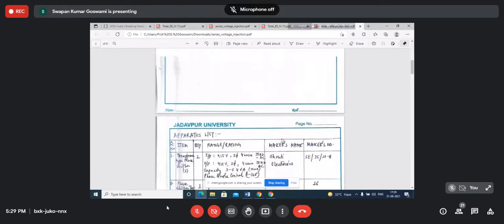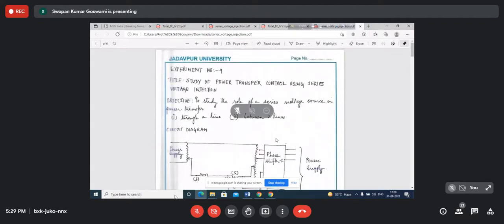Yeah, it is done, but the problem is that in this case, we are simulating here. This source is taken from the laboratory. What is the power supply available? That means from the same source we have taken. Physically, what will happen? Physically, this will be the end of a generator. This will be the end of a generator at a very distant location. Okay, that isolation, creating impedance in between, is not possible in the laboratory. That's why we don't have that much control.